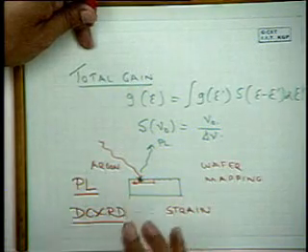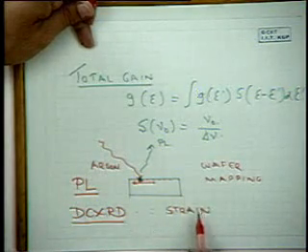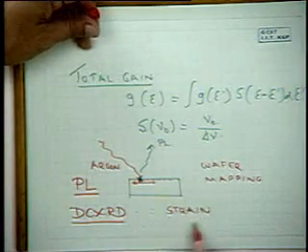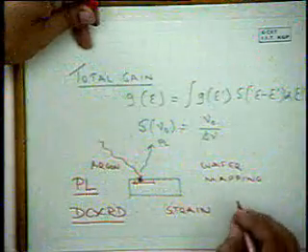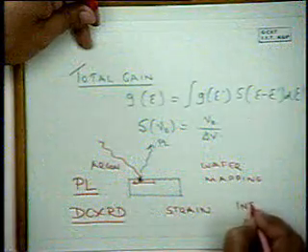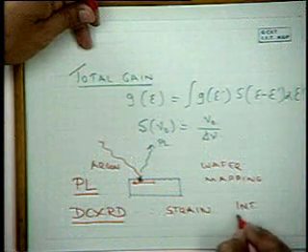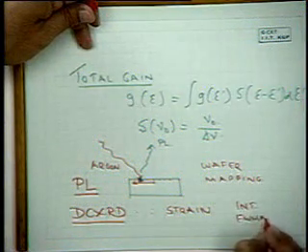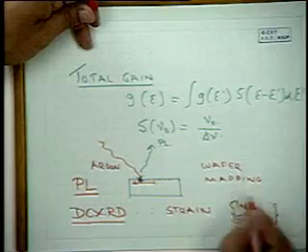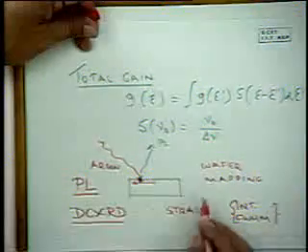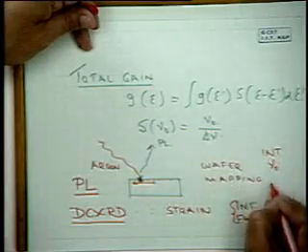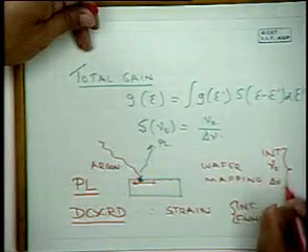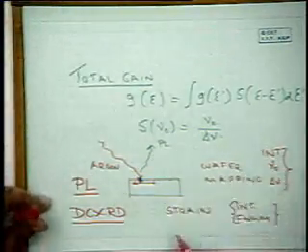We have actually done this and plotted the DC XRD. Here also we measure the intensity and the line width. With PL, we measure the intensity, nu 0 and delta nu. So experimentally these give us information about the quality of the layer.